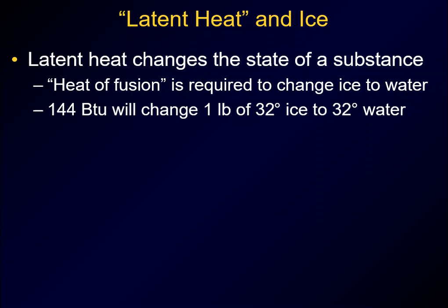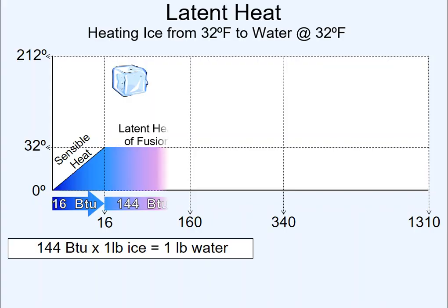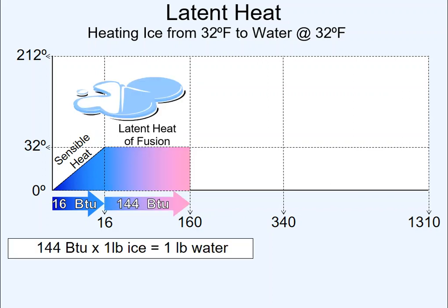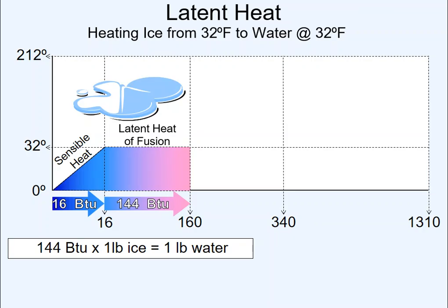Because it's colder, heat is attracted to it, but it still can't capture enough heat just through the fact that it's cold. What really does the most work is the latent part. The fact that it's cold, going from 70 to 40, that's 30 to 35 degrees of sensible heat. Sensible does some work, but if you look at this little graphic here, sensible heat versus latent heat.